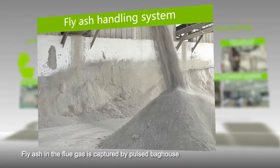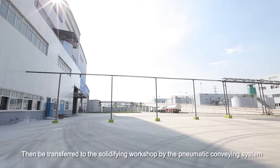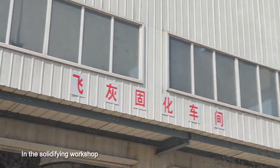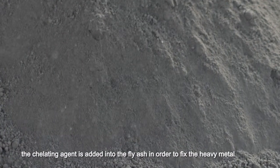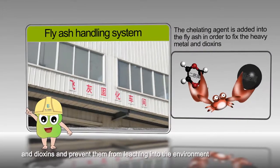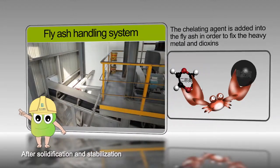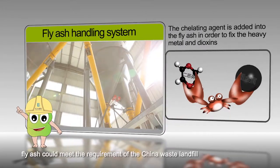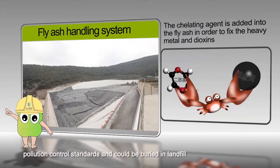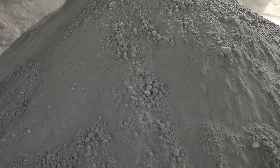Fly ash in the flue gas is captured by the pulsed baghouse, then is transferred to the solidifying workshop by the pneumatic conveying system. In the solidifying workshop, the chelating agent is added into the fly ash in order to fix the heavy metal and dioxins and prevent them from leaking into the environment. After solidification and stabilization, fly ash could meet the requirement of the China Waste Landfill Pollution Control Standards and could be buried in landfill. 6.